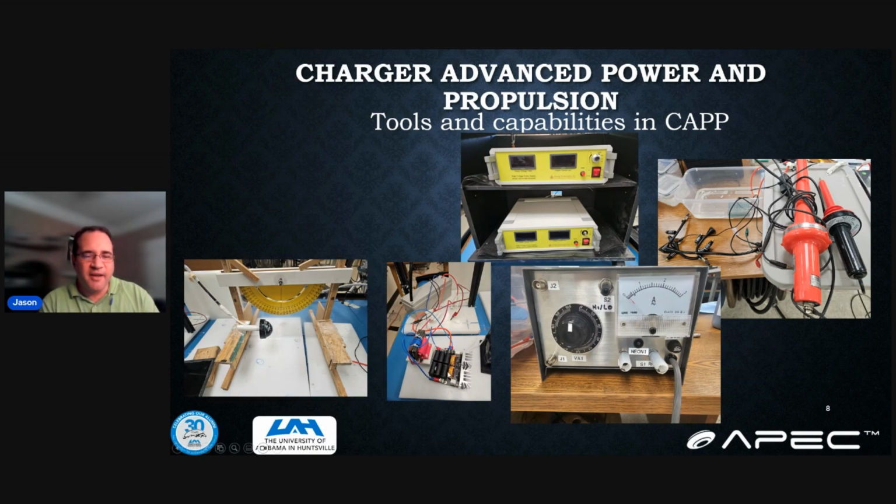Then we have a more experimental one, which basically involves a signal generator, a ZVS flyback driver, a flyback transformer, and then a Cockcroft-Walton voltage multiplier, which gets us somewhere between 200 and 400,000 volts. We're in the process of trying to measure it because it's not an instrumented supply; it's highly experimental.